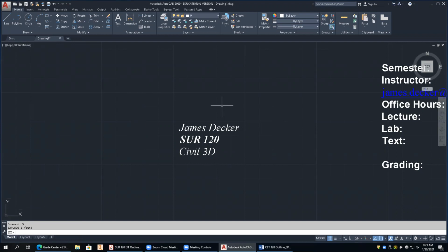So when we exploded it, it drops down from a higher type of object to a lower type of object. So what it went from is an MText. If you click on this now, you notice these are now single line pieces of text. They're all separate.